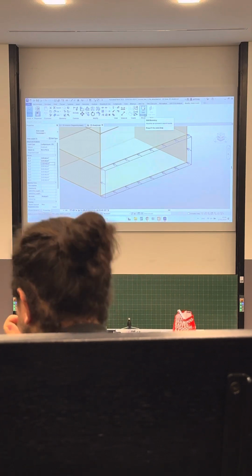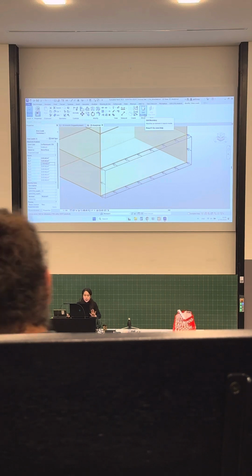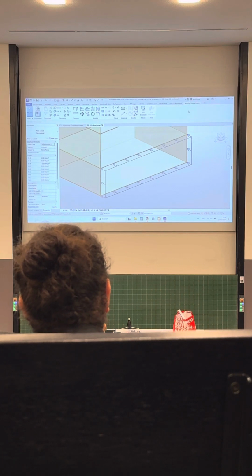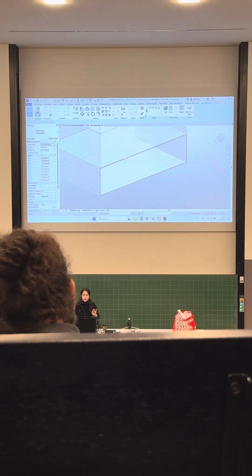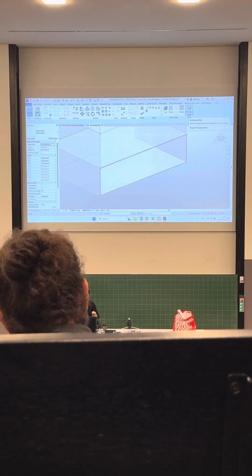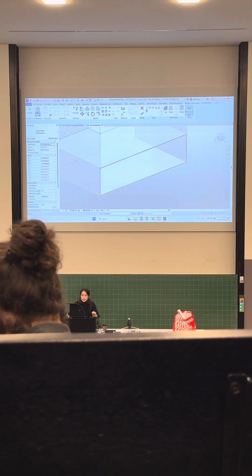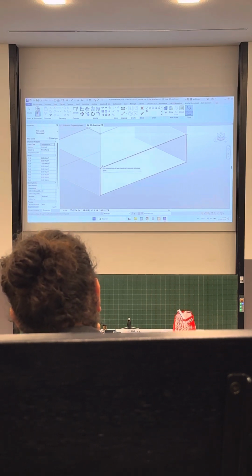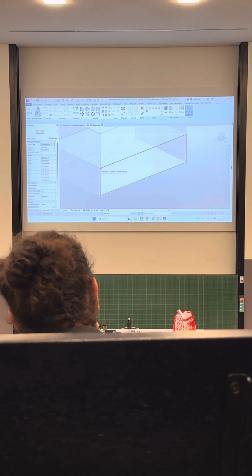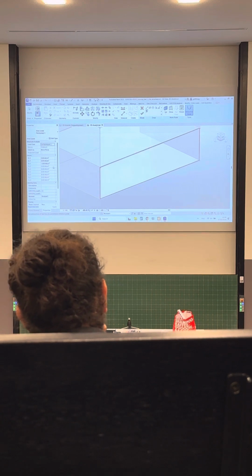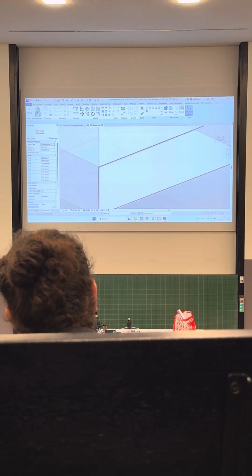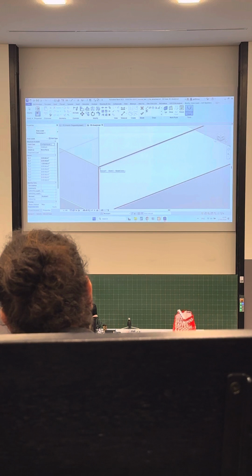And another important thing now, after we created the area load, we want to make it variable. We click on our area load, go into the edit boundary, and there's such a tool as a reference point. This we need for referencing, like you work with the topography the similar way, you define a point that you would like to have a different value. Because it's -2 and I want it to be on the bottom, I will add another point on top here.